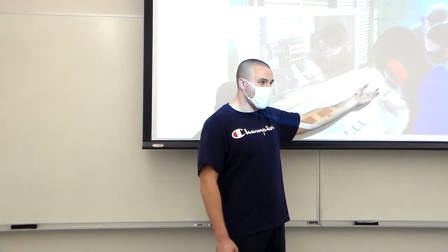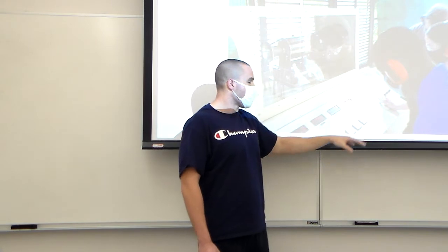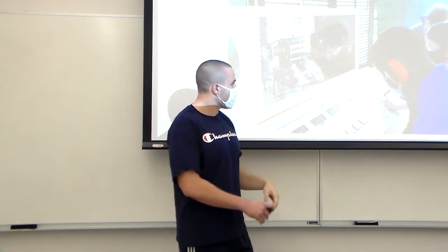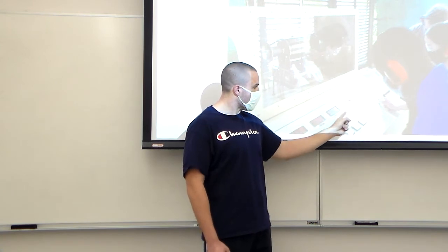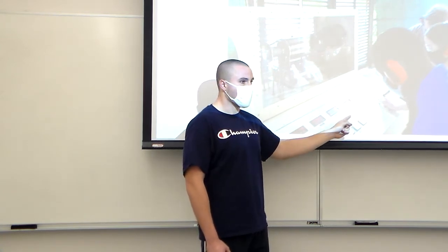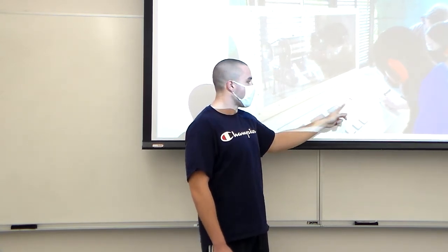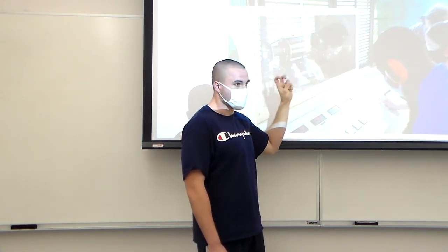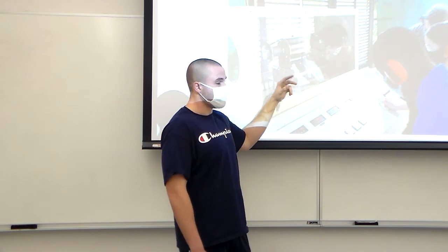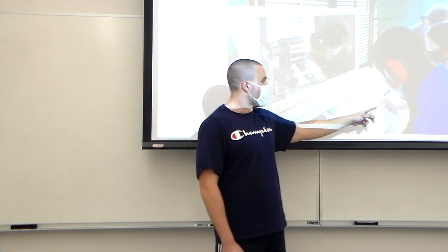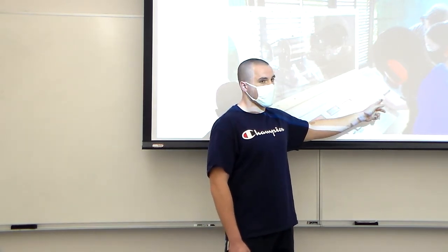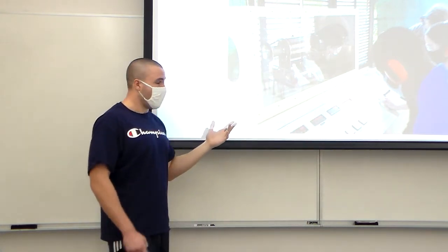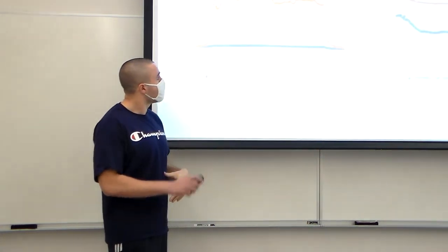You want to bring it up to throttle, and you're going to run it to about 43,000 RPM. Now, when that happens, this little display board here will say the word run on it. Once it hits run, you now know that this turbine has hit essentially steady state. And once this hits steady state, you can start playing with the load lever to see how the generator is affected. That was overall how we ran this entire experiment.